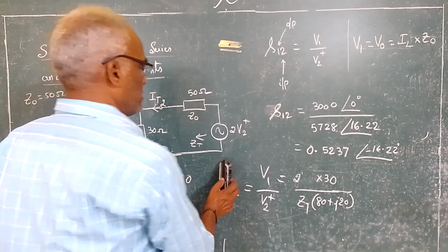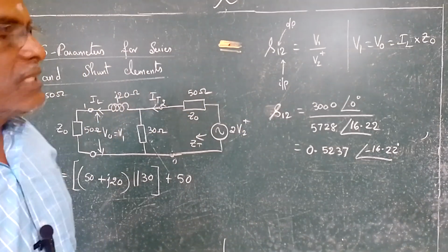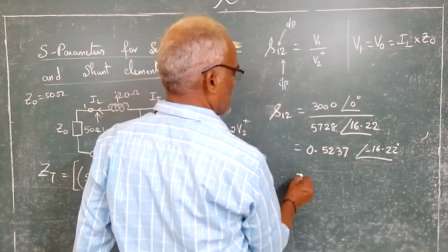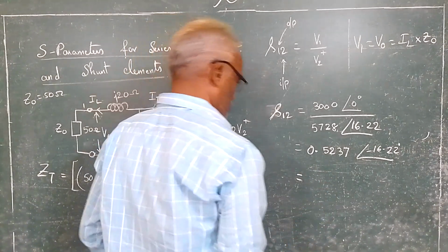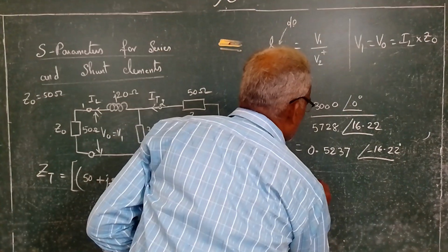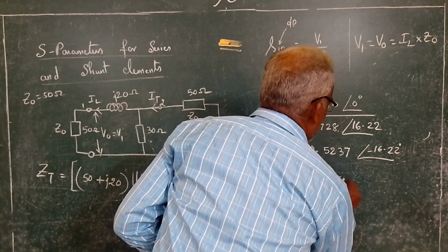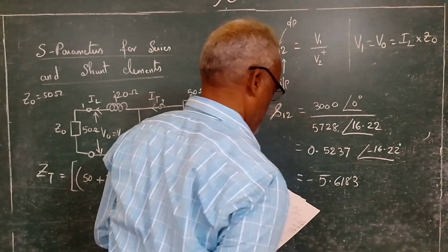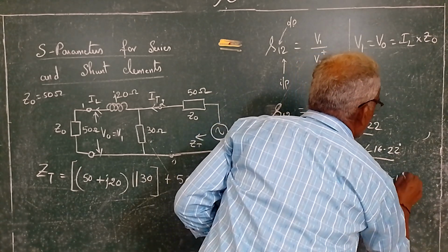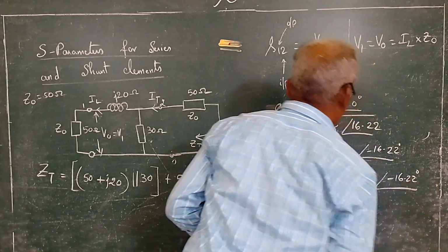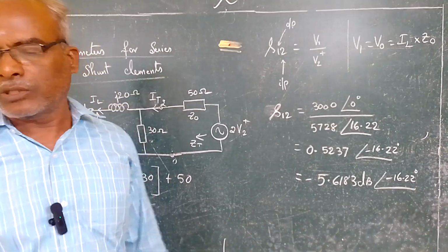Finally, this itself is the answer. If you want the answer in decibels, 20 log of this value. So you will be getting minus 5.6183 dB. The angle will be the same, minus 16.22 degrees. So this will be the answer for S12.